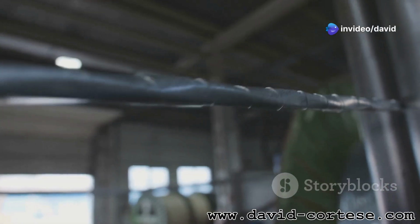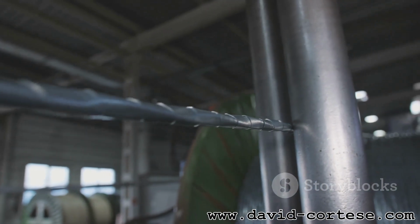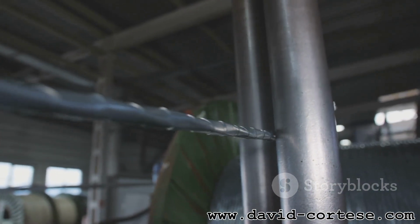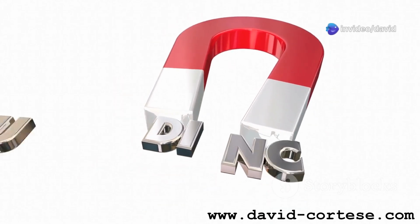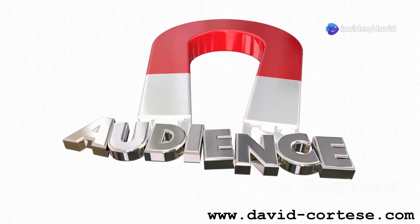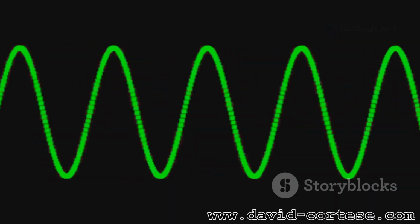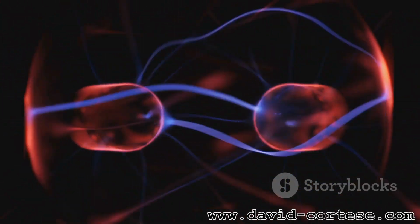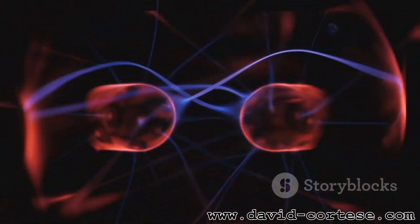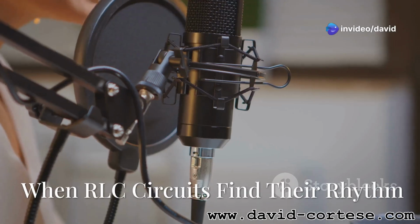As the capacitor charges, the voltage across it increases, eventually reaching a point where the current through the inductor starts to decrease. However, the inductor's magnetic field now starts to collapse, inducing a current that tries to keep flowing. This interplay between the capacitor's electric field and the inductor's magnetic field creates oscillations. The energy sloshes back and forth between the capacitor and the inductor, with the resistor gradually dissipating the energy as heat.